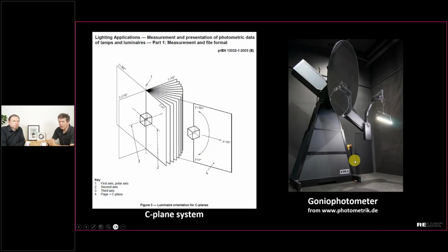For example, with many luminaires you typically have variances in your measurements, but to make, for example, the symmetrization of a luminaire, it may be really helpful for the planning and for the calculation program. A series of symmetrized files is better than any raw measurement data as it dropped out from the photometer.